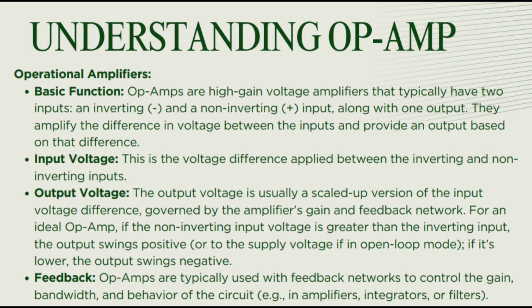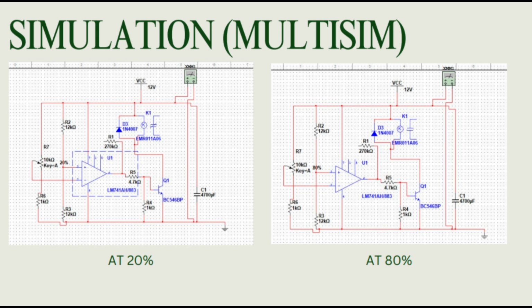The threshold level is a reference voltage. When the input signal crosses this threshold, the output changes state, triggering a response. This makes comparators ideal for interfacing analog signals with digital circuits, enabling actions like switching or triggering based on specific voltage levels.